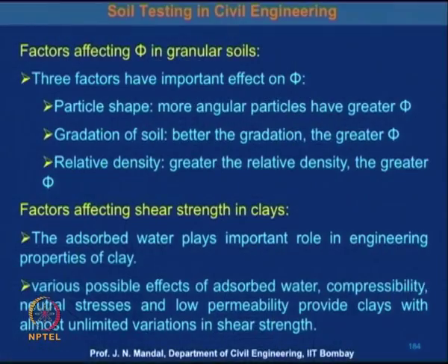The critical combination of shear and normal stress, when plotted on a sigma and tau coordinate, forms a line that is known as the Mohr envelope of rupture. Failure will occur if for a given value of sigma the shear stress exceeds that value. So, we can draw the Mohr envelope line.